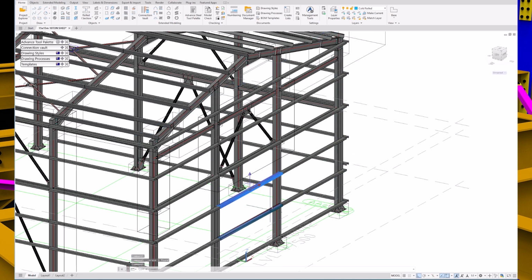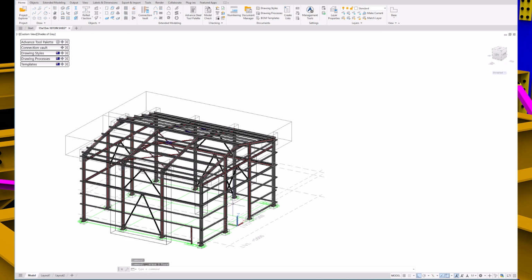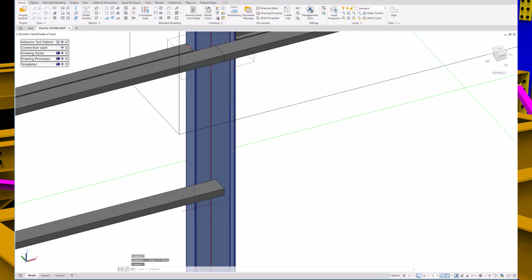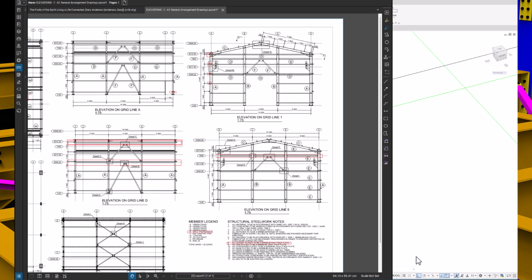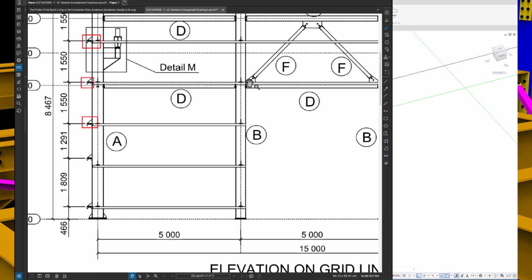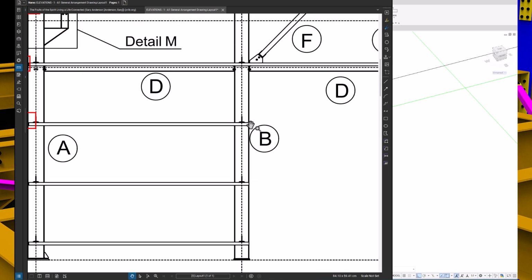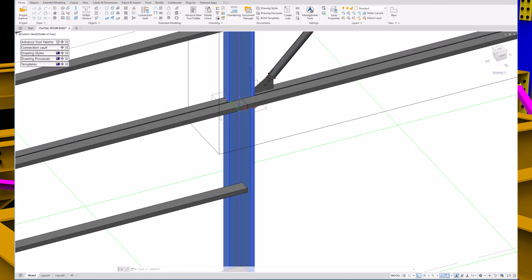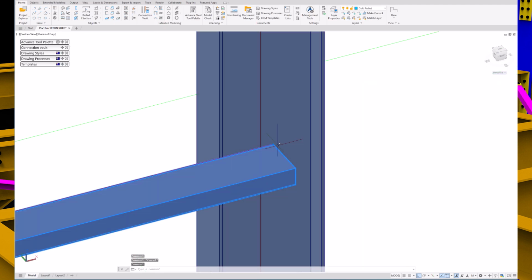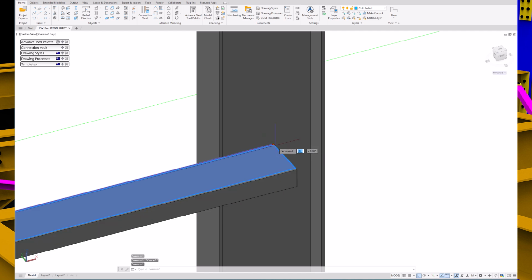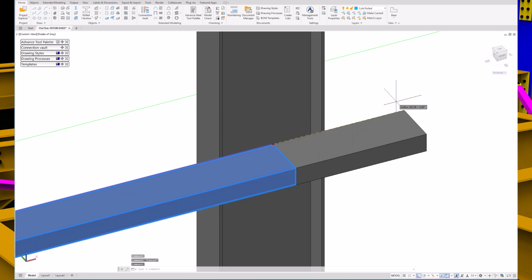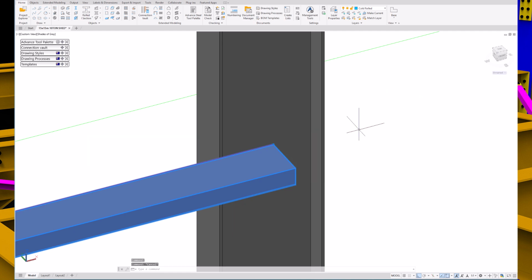Now we can delete them manually, and then enter. Now we just need to extend. If we check our PDF, we go to that view. As you can see, our pair lines are going to the other flange. Okay, so select the pair line, select the node, then drag to the side where you want to extend, and then let's just check this.